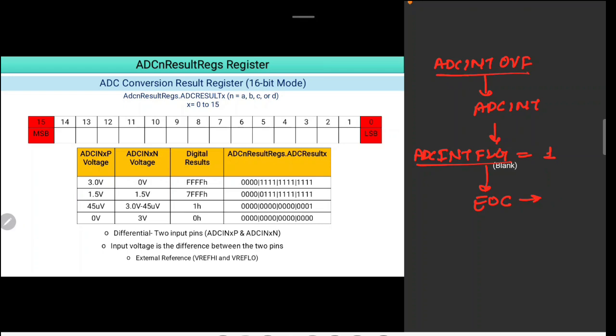So when this bit equals 0, that means no ADC interrupt overflow event was detected, and when this bit equals 1, that means an overflow condition is detected. The overflow bit does not care about the continuous mode bit state, and the overflow condition is generated irrespective of the mode selections. Then how do we clear these overflow conditions?